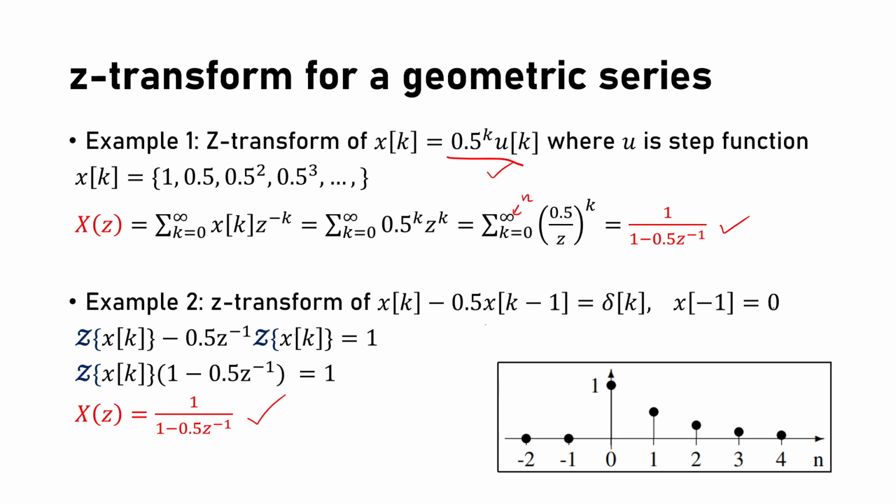Then if you want to solve a difference equation, you transform it into the Z domain, do some manipulation on the polynomial, and make the canonical form that you can compare to the table. Then you can immediately use a lookup table as the inverse Z. You don't need to apply the formulation of the inverse Z, but theoretically there exists one. It's like a Cauchy integral or something like that. Yeah, it's very complicated.